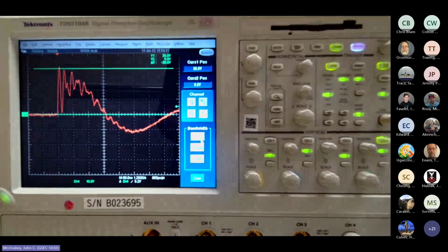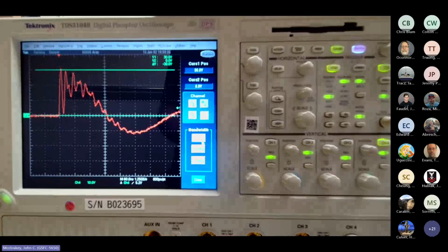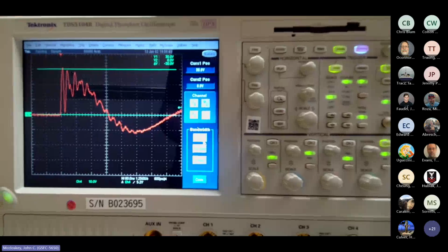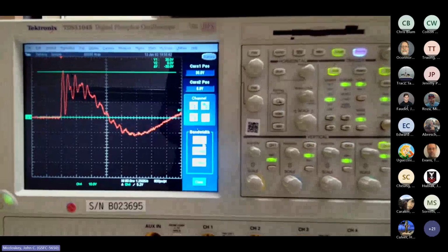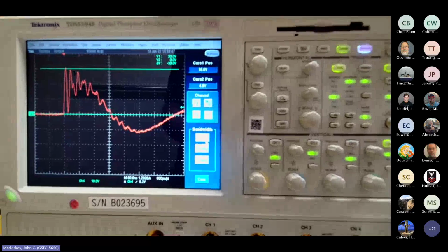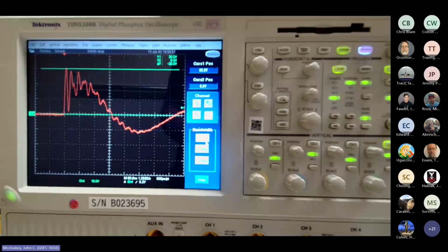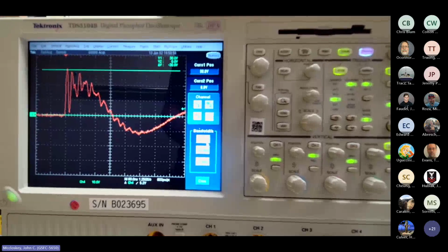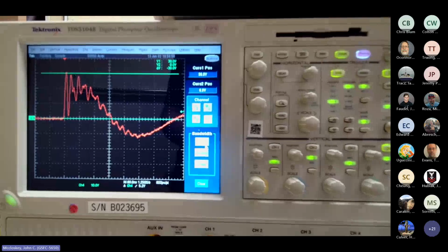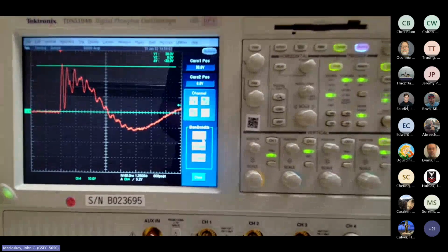When we got to the spacecraft level EMI test, I wanted to characterize the turn on and turn off transients on the power bus as we were turning stuff on and off. And this was not a specific requirement. This was something I specifically wanted to do for engineering data. It took a little time just to set up the scope and everything like that, but it was no additional time in the overall scheme of the comprehensive performance test at spacecraft level.